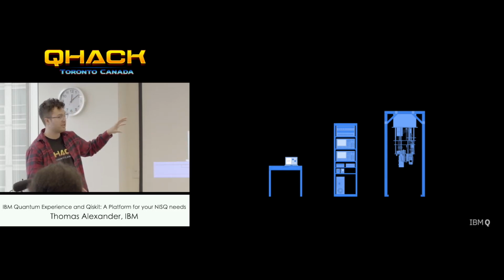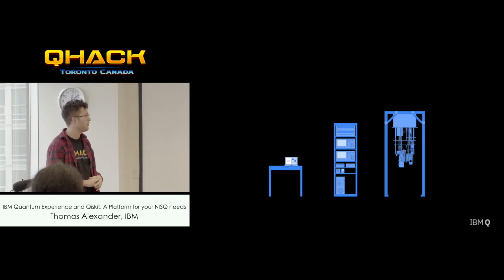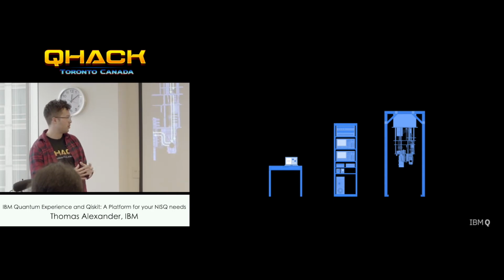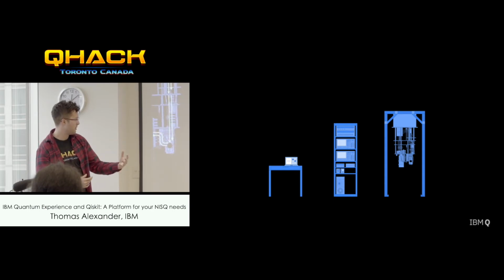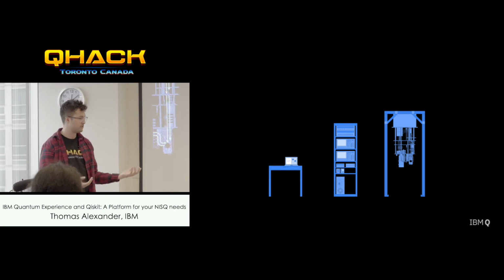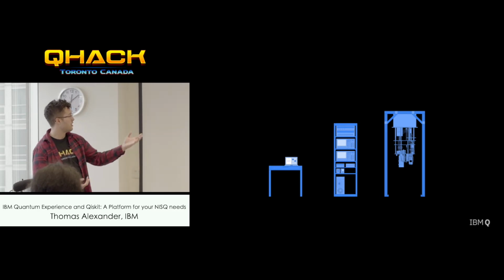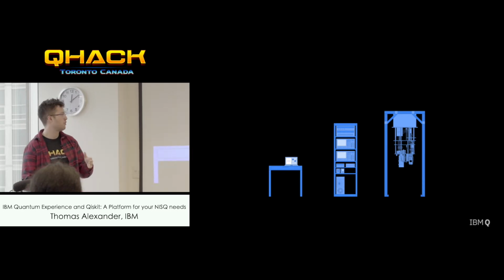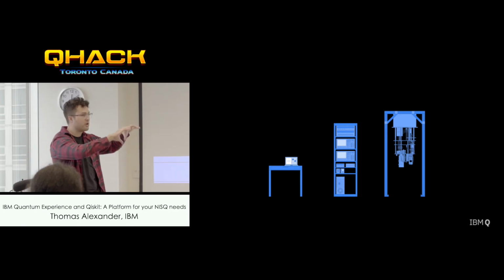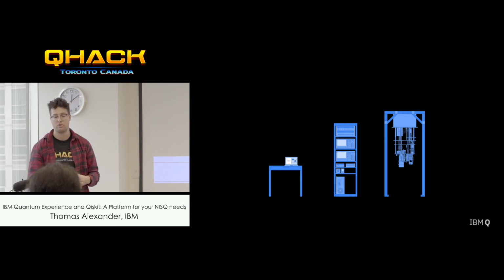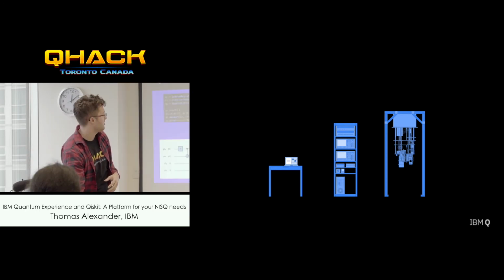So in Qiskit, you send a program down through the cloud, and it's going to interface with the quantum control electronics. This is kind of an antiquated system, but these are going to send out microwave pulses into our quantum computer, and they're going to go down and interact with the qubits, say manipulate them with a gate or do a measurement, and we're going to get back out a classical signal that's going to be amplified in the fridge. Then the classical control electronics are going to take that signal, sample it, and say, is this a 0 or a 1, and then this result comes back to you. So underlying what a quantum computer is, is this classical control that needs to manipulate the systems.